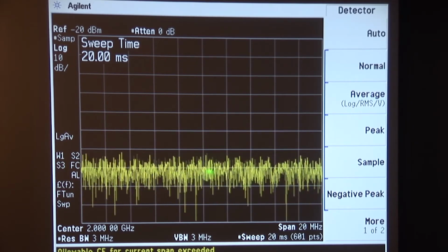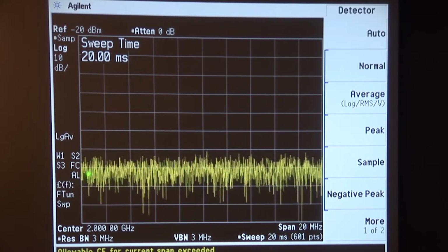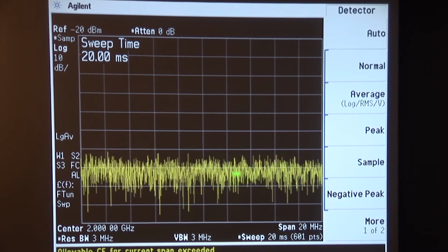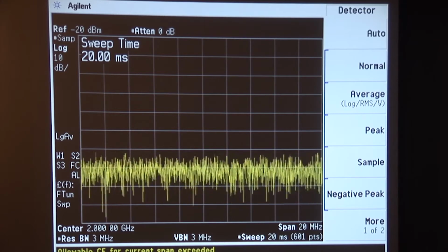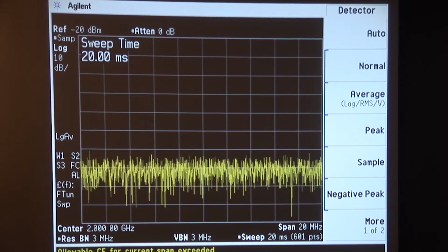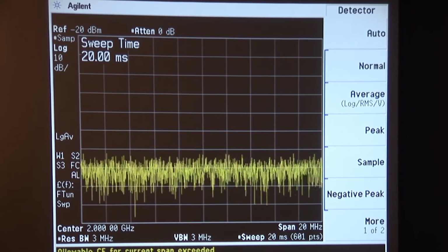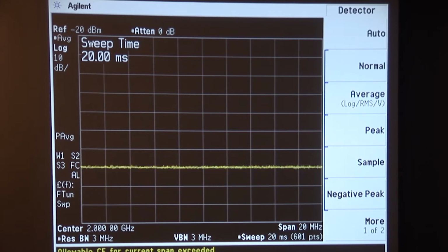The random point comes off at the end of the sampling interval for the analog to digital converter for each one of these bins every few microseconds. And what we're seeing here, of course, is the noise characteristic that we saw in the last talk. But to look at the carrier wave, although it's not terribly important to pick this particular detection, let's go to average detection. So we pick this selection right here, average. And now we will go ahead and turn on a carrier wave signal.